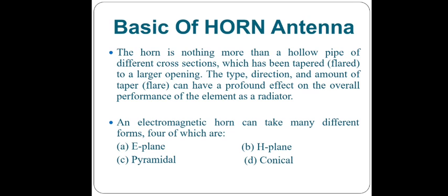When coming to the antenna, the electrical signal should be transformed to an electromagnetic wave by using the antenna. So here the flared out waveguide, right? Here the losses are reduced and the focusing of the beam improves. A horn antenna may be considered as a flared out waveguide, you already know that, by which the directivity is improved and the diffraction is reduced. That is the main function of the horn antenna.